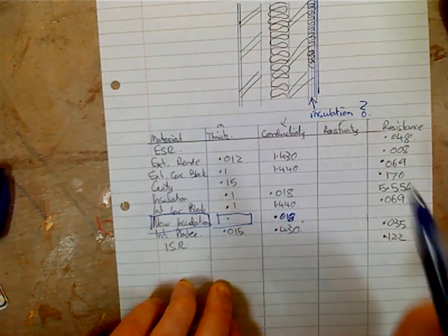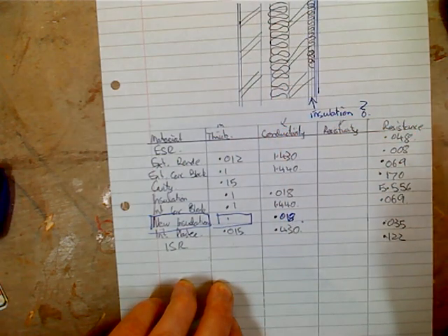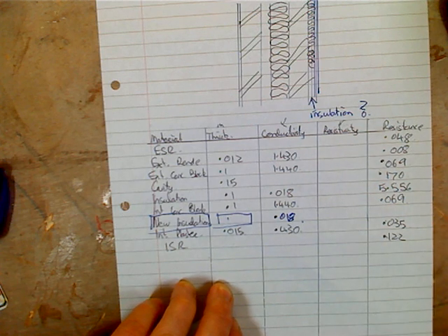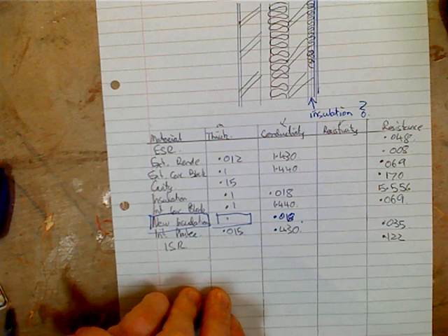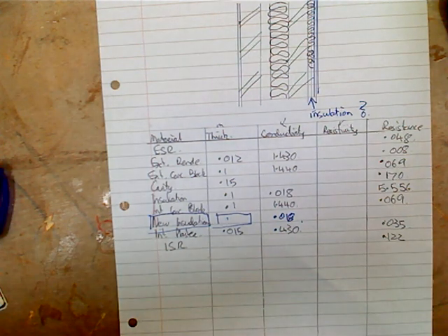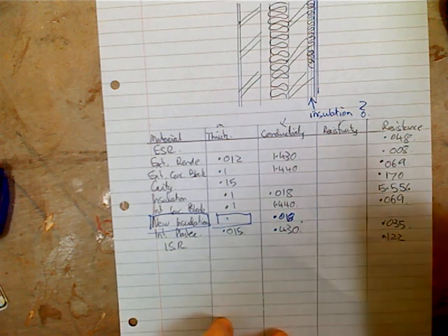So the current value for a wall is 0.15 watts per meter squared per degree Celsius, right? So that's the value. So I have to make my wall meet that value. It's currently at 0.165. I need to reduce it. So I need to add insulation, but how much do I need to get to that value? Does that make sense? And it mightn't be a nice round number. So if I add more than that, then I'm going to get a lower value, which is going to be better. Does that make sense? Exactly 0.5. So I'm putting in exactly 0.5. Yeah. Okay? So how does this work?